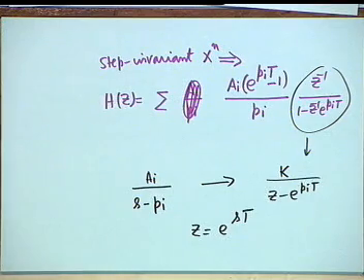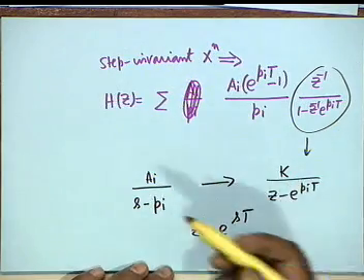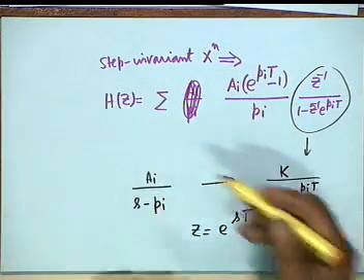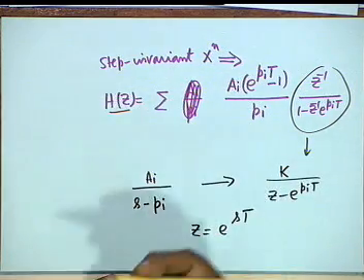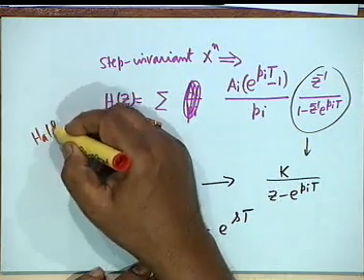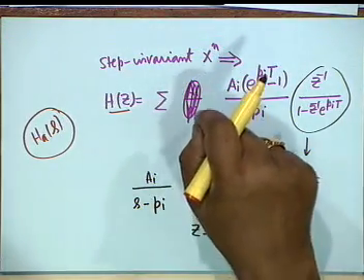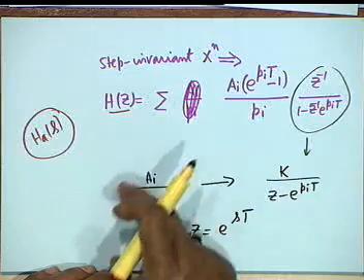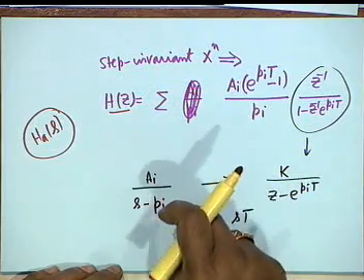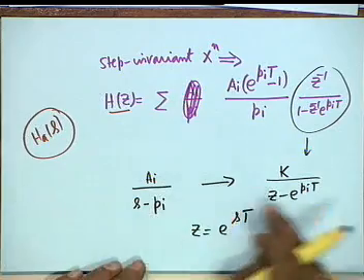To k divided by z minus pi. Yeah, but ultimately we have multiplied by 1 minus z inverse. We have obtained the impulse response. Impulse response is the same. Laplace transform is H_A of S. 1 by S we multiplied to obtain the step response. Then we sampled the step response. We took the Z transform and then we multiplied by 1 minus Z inverse. Right? So ultimately a pole, a residue and a pole factor in the partial fraction expansion has gone into this.